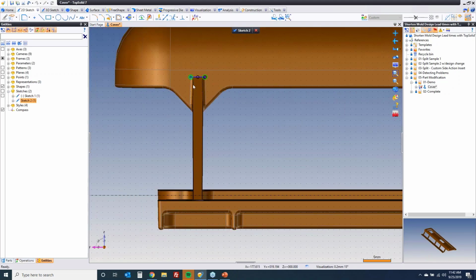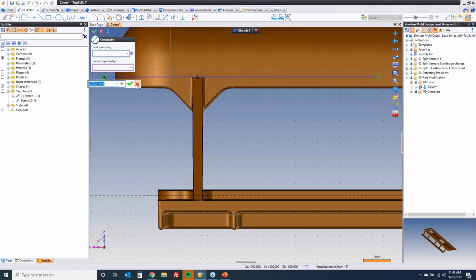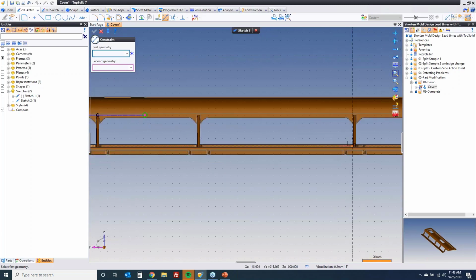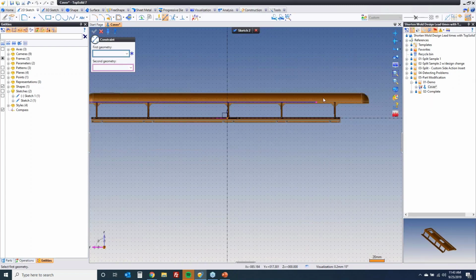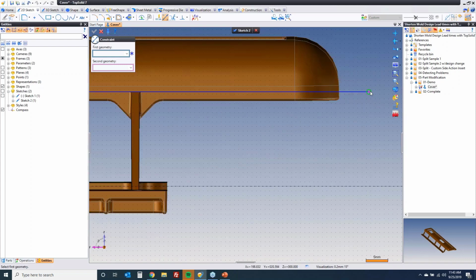And again, I'm going to remove the coincident relationship there and there. I'm going to extend this out that way. We'll extend this out that way for now. I'm going to add a quick dimension just because I always like to be fully constrained. Sure, why not? Don't really care what the size is. Notice I'm in my dimension tool. I can still resize geometry while I'm in it. That's kind of awesome. We can go there, come down. Sure, I like round numbers.